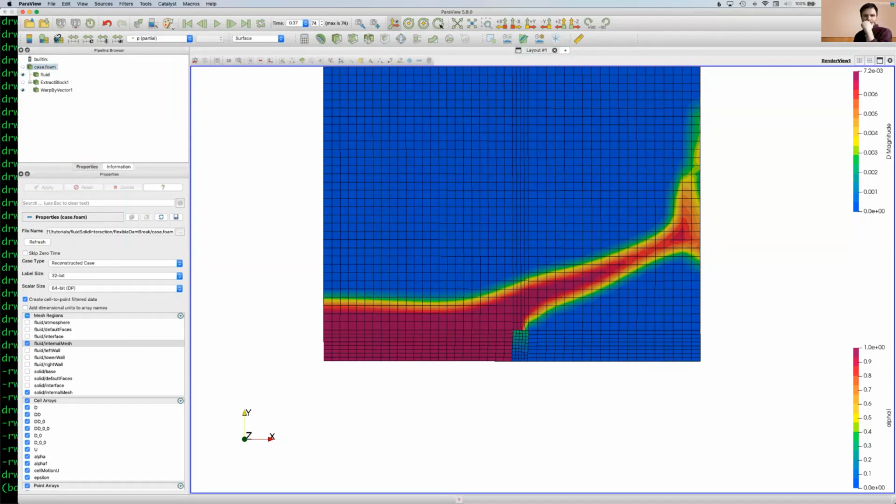So can rupture be modeled? I never answered that. There is a test case, and there are fracture test cases, simple fracture test cases. I spent some time modeling fractures in OpenFOAM. For composites, it's pretty difficult, to be honest. There are a lot of convergence problems.